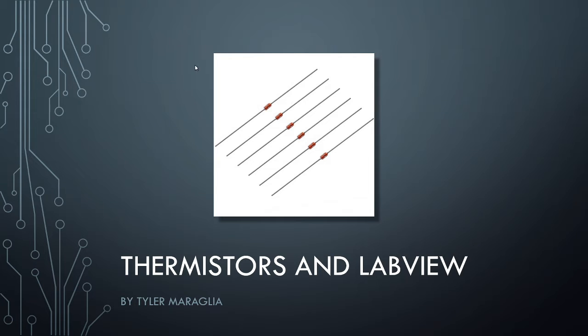I want to start by saying I had to take a little bit of a different approach to this lab as it was laid out. The thermistors that were required for the course were on back order when I tried to order everything. So I ended up ordering these off Amazon. These are from GeekFun. They are NTC MF58 3950B glass 10,000 ohm thermistors. We'll see later that they didn't have all the information that was needed, but there was a workaround for that. There's other ways to calculate the resistance of a thermistor that I went into.